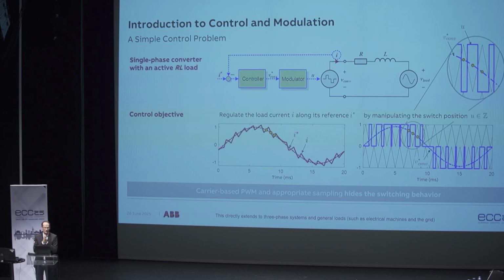Now, this also then masks the switching and limits the performance of the controller, because you end up with a delay, and the controller cannot directly influence the switching, so the switching is typically somehow ad hoc. And switching is always expensive. You always have losses whenever you switch. And in this very simplistic way, you pay a significant price to get the simplicity.